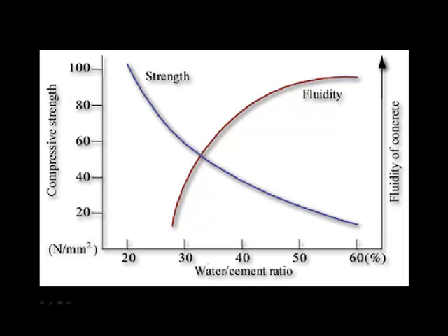The mix used in a footing is probably a lower strength mix than a mix used in a wall, and in a concrete bridge deck, the concrete mix may have slightly different proportions. And for special applications, like when you're pumping concrete, that requires a different ratio of components.